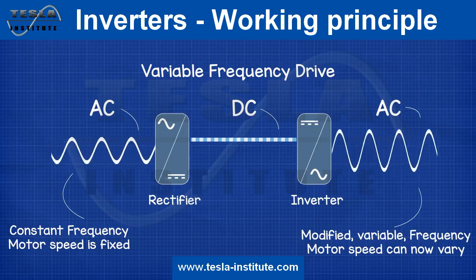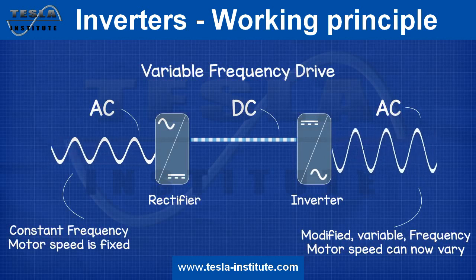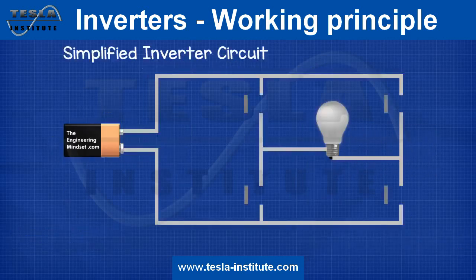This is partly how the Danfoss Optima Plus inverter condensing unit works. It has a very clever control loop which is measuring the cooling load and then changes the speed of the motor, which changes the speed of the scroll compressor, and that increases or decreases the cooling capacity to match the load, which results in precise temperature control as well as energy savings. So how do they work?